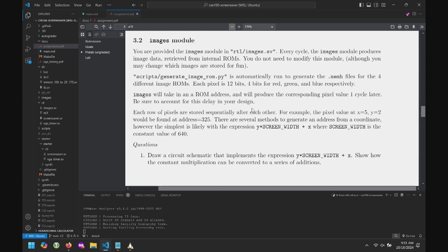When you have a very large RAM, it helps to have a clock signal in it, and it's for kind of analog reasons. I won't go into the circuit schematic of how to implement a memory, but there are amplifiers and things that operate with a clock, and so your large RAMs require a clock. That means when you try to read out data, does it happen instantly, or how long does it take to read out data from a large RAM?